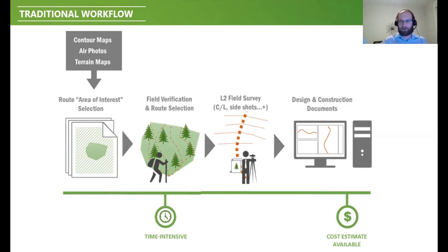You can say, oh, I'm going to average this over this for such a difference, but you don't look at the details of, I've actually got a big cut in there, a big fill in there, and we can't just push out because that's going to send a big fill slope down to where we don't want it.